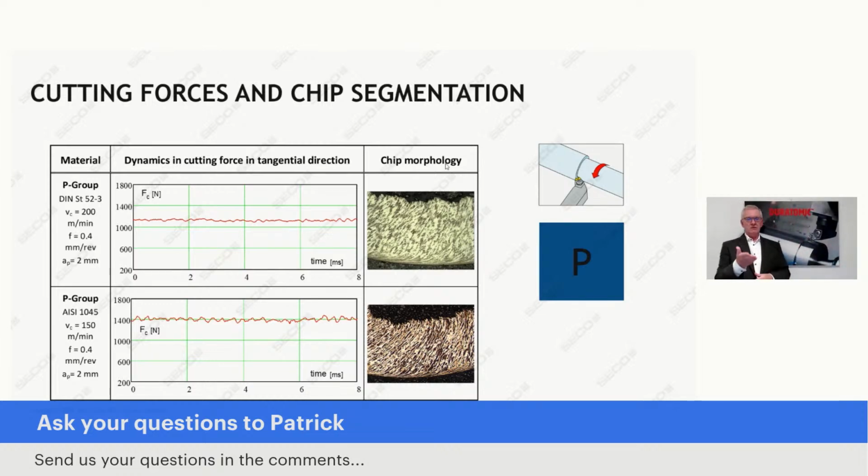On the contrary, at the bottom you see a steel which has somewhat higher hardness. We see that with higher hardness, the original flat line starts to vary a bit. And that variation is kind of indicating the risk for having vibrations is growing.